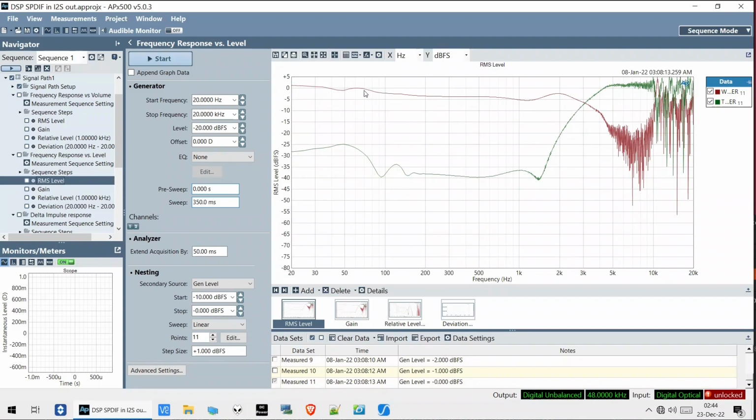We're seeing that it runs into 0 dBFS, and we have a big problem here because we saw the curves massively changing. But what you can also notice, if you look at the tweeter signal, is that the tweeter signal is also completely distorted now, and even the woofer low pass filtering is completely distorted. And this is quite interesting, what's going on here.